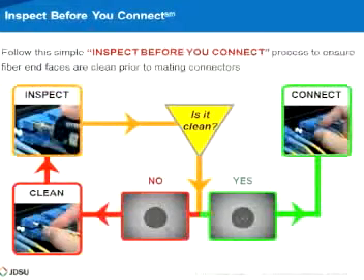Second, no cleaning tool is ideal, meaning that it can introduce contamination on the fiber, and the only way to verify that is by inspection. Third, what if that connector is damaged? Before it was handled by you, it was probably handled by someone in manufacturing, then system integration, pulling the cable. So you're probably the fifth or sixth person touching this fiber. I personally don't believe that everybody before me followed the right procedures, so it's better to be safe and verify the fiber is clean and not damaged, and not assume someone else's mistake.